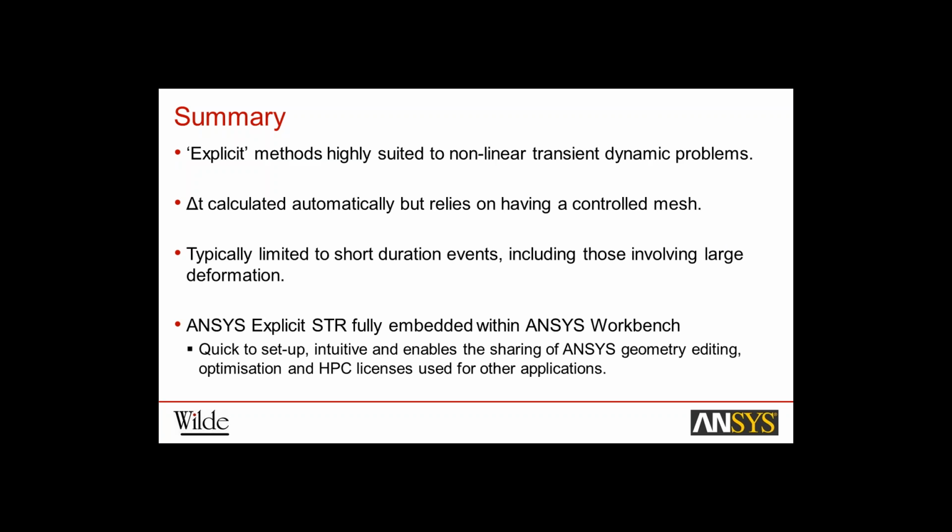There's a lot of benefits of the Ansys Explicit STR solution. And one of those is that it automatically takes care of the time step size. However, you always have to be mindful with any simulation on having a good quality mesh, as that can affect that size and ultimately both runtime and your results.